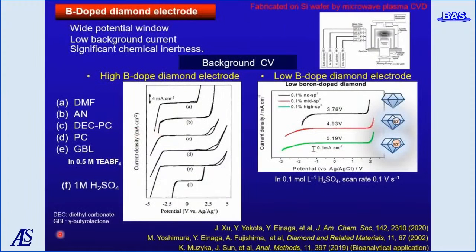Boron-doped diamond electrode, abbreviated BDD here, has attracted much attention as a new electrode material, in particular for biological sensor applications. BDD consists of a diamond in which approximately one atom in 1,000 has been replaced by boron, giving the material p-type semiconductive properties and yielding the hardest conductive carbon materials.